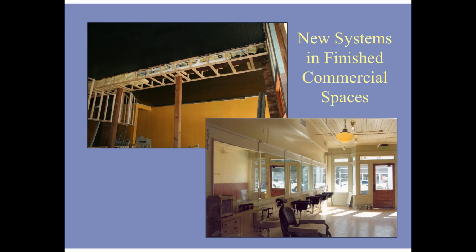Top left, all systems were grouped along a plain beam at the column line, and the soffit will be finished with gypsum board and painted to match the ceiling. This solution may not be appropriate where a beam is architecturally distinguished by crown molding or other features. At the bottom right, the soffit is located along the interior partition wall.